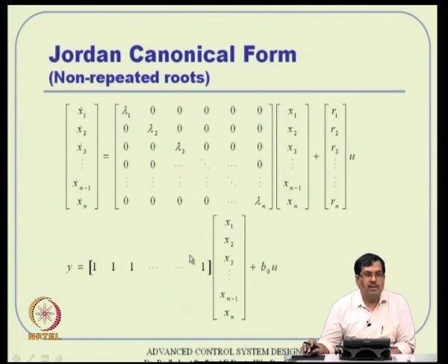Okay. However, for the B, C and D matrices, we have to be slightly careful actually. Earlier the B matrix turned out to be 0 0 0 0, with the last element being some number, here all the elements will have some number actually. And why does that happen? That primarily happens because of the change of the definition of x 1, x 2, x 3. It is no more your first companion form, where the state variables normally carry direct nice physical meaning, right.